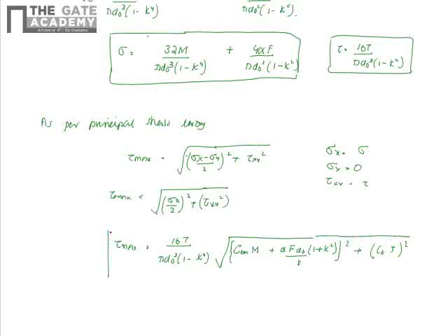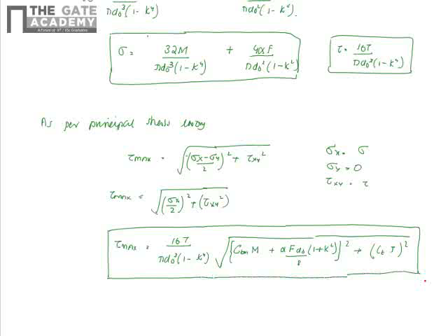This is the maximum shear stress going to come in the shaft when it is having all the types of loading, that is bending load, and then we have the axial load, and then we have the torsional loads. And all loads are acting together on the shaft. Maximum shear stress is given by this relation, where T is the torque at any section, Do is the outer diameter of the shaft, K is the ratio of inner diameter to the outer diameter, CBM is the factor modifying the bending moment, and Ct is the modifying factor for the torque to account for the dynamic effects.